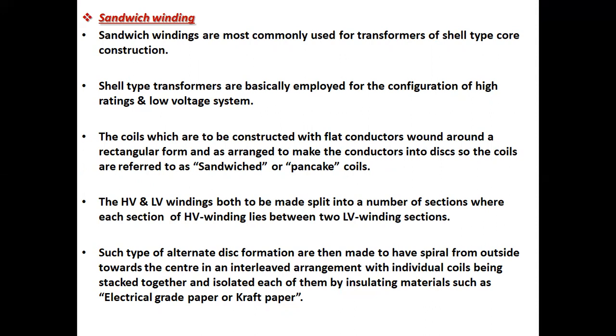Such alternate disc formations are then made to spiral from outside towards the center in an interleaved arrangement, with individual coils being stacked together and each of them isolated by insulating materials such as electrical grade paper or kraft paper.